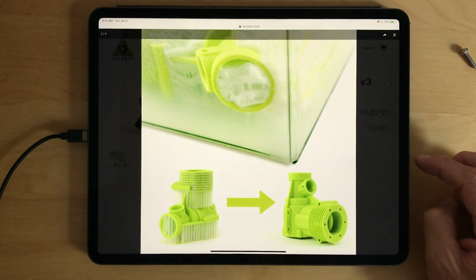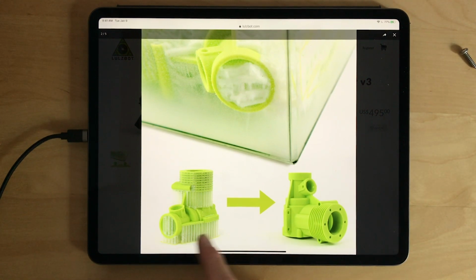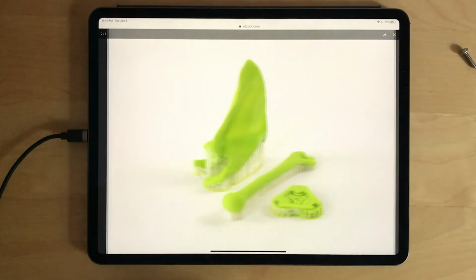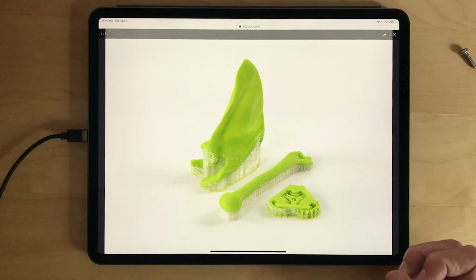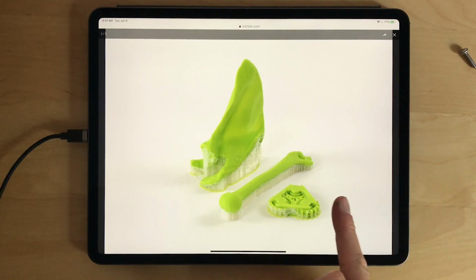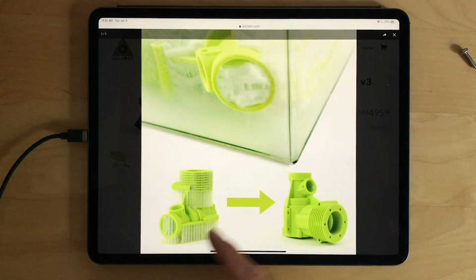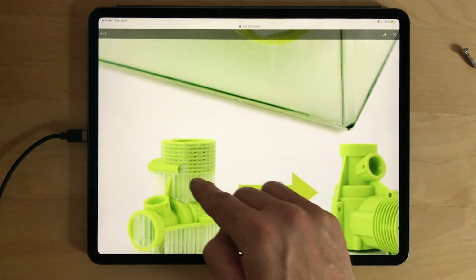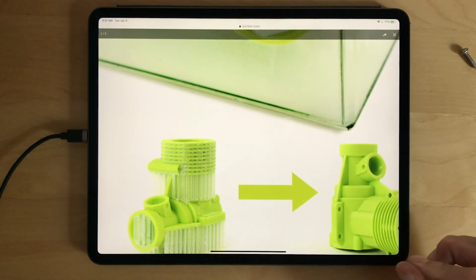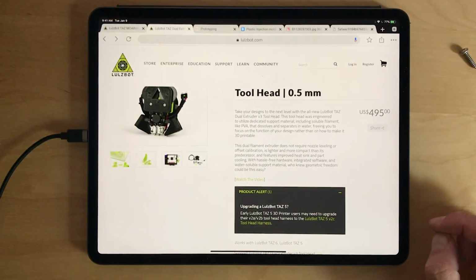And then you can even, instead of using a build material, use a support material. In this case, do you see that translucent one? That can be dissolved, so you wash it away. Obviously, this is more meant for finer prints, so the prints will take a little bit longer because it doesn't use this big nozzle, but you will end up with less de-support. In particular here, that's kind of genius, in these small details, the support can be put in and later washed out, so you don't have to use a plier to get it out.